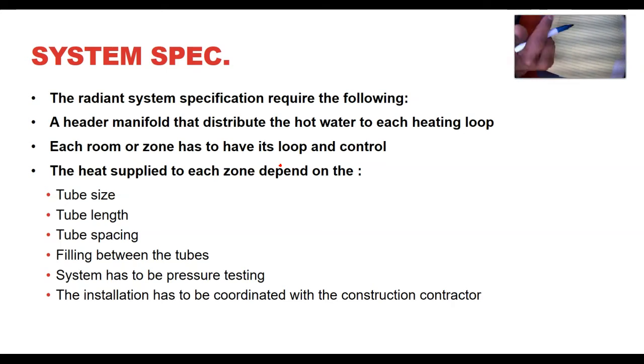So if we think of this as a room, and I'm trying to heat this room using radiant floor heating, again, think of the equation, okay? Radiation rate times area times delta T. Let's say we fixed the area, we cannot change it, and the temperature inside we cannot change, so we can only change the temperature of the water going into those tubes, right? What goes into the calculation of the radiation rate? So chances are you're going to buy a preset radiation rate for that floor heating.